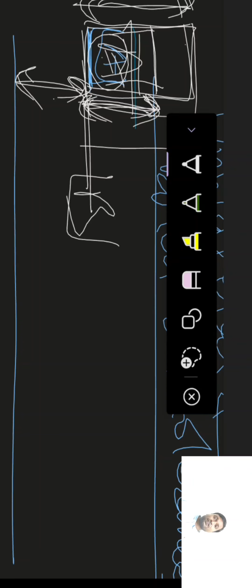Similarly, come to ZA, ZB, ZC, or you can come to P, R, S, T, V. All these fundamental deviations for the hole will be represented below the zero line, that is, on one side of the zero line. Then these are also unilateral tolerances. Holes with fundamental deviation P, R, S, ZA, ZB, ZC will be below the zero line and will be called unilateral tolerance.